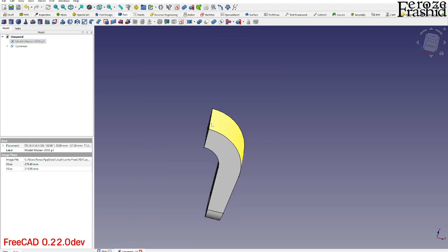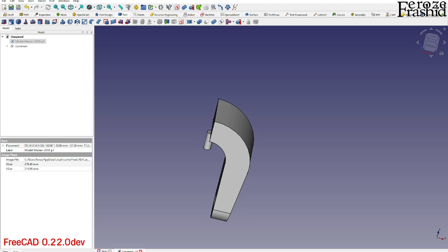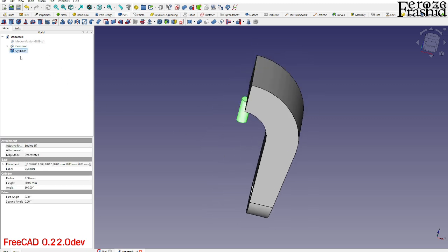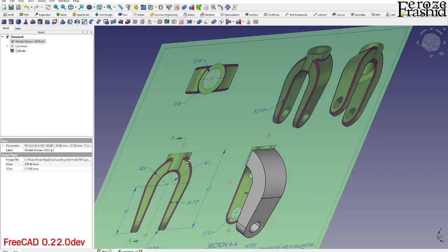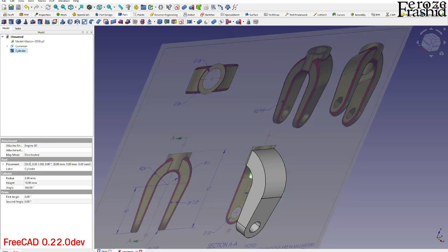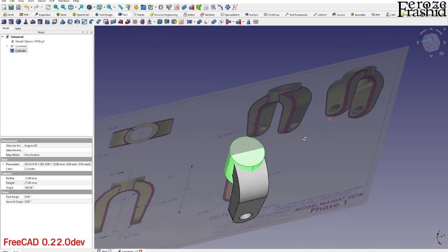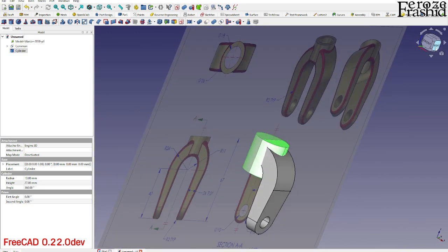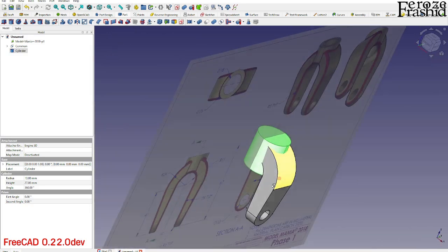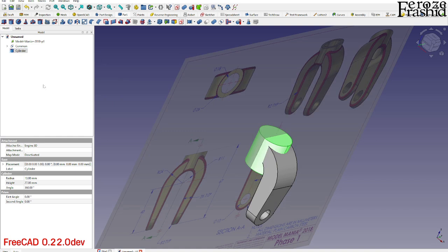I don't want to build that as a tube. I'll build a cylinder, and that cylinder will be radius 18 and 26 diameter, right? So the outside would be radius 13, and I think the height would be 27. I just used it a minute ago. Okay, so there is our one cylinder. I'm going to rename that as large,